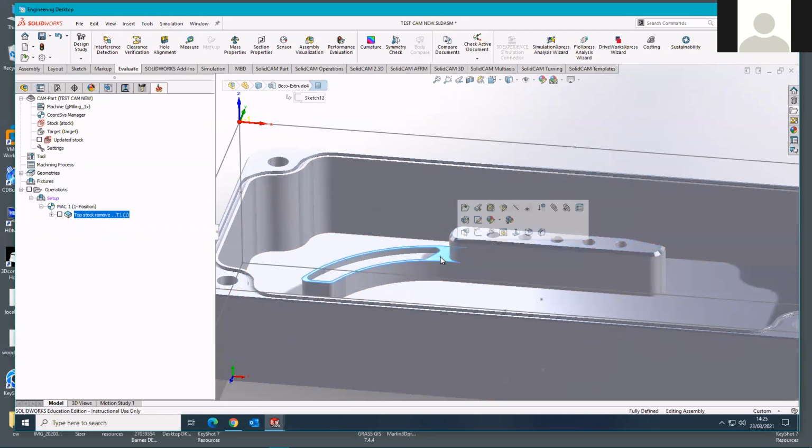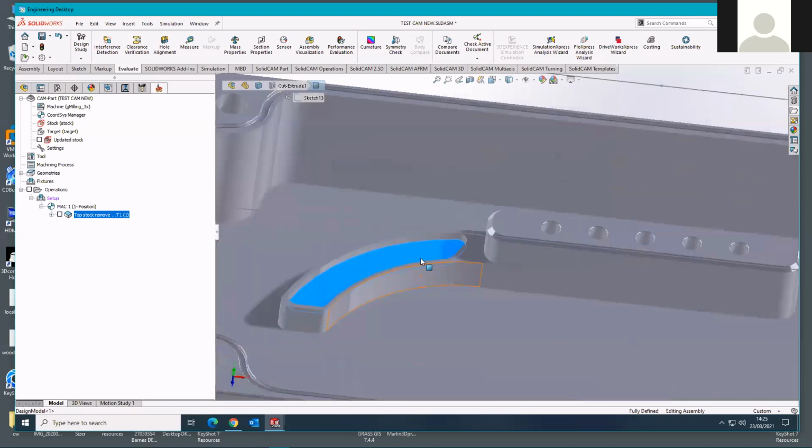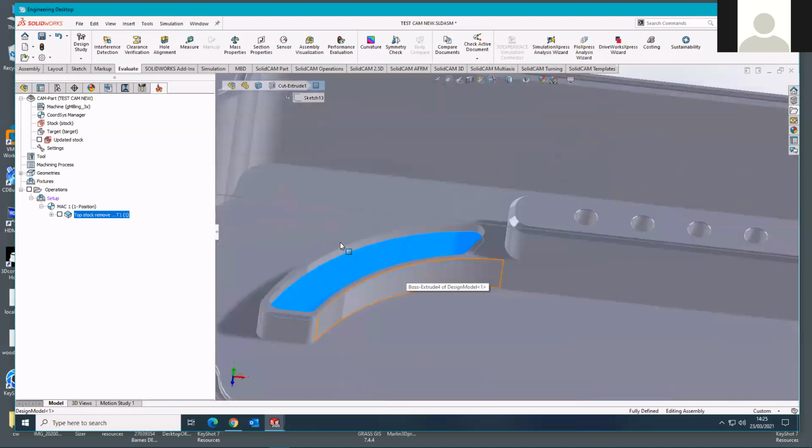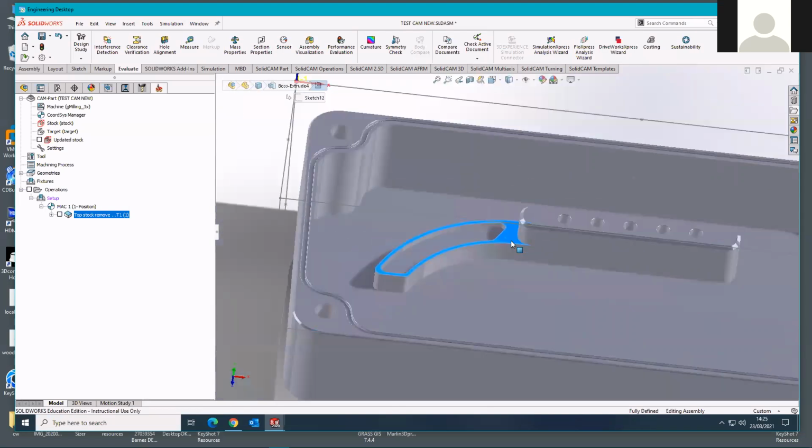And then we'll do a third one, which will just address this little pocket inside there. So you can see that there's a self-contained pocket shape. We'll address that one, but the tool that addresses that will begin at that level there, because these pocketing operations are gradually getting deeper and deeper and addressing the various features that occur further and further down on the Z level in this larger pocket.